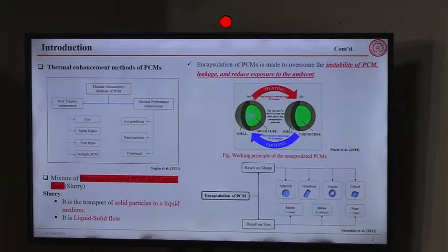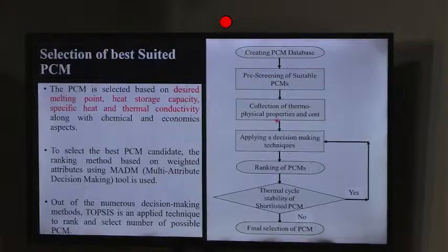With this hydrophilic sheath or copolymeric shell which you are making, you are enhancing the overall accessibility of the wax, and you can mix it with concrete or mix it with water to make a slurry and then exchange the heat from one to another. So you can think of how the hydrophobicity of wax can be converted to a miscible slurry or made more user friendly, for maximum utilization of the capacity of the system.